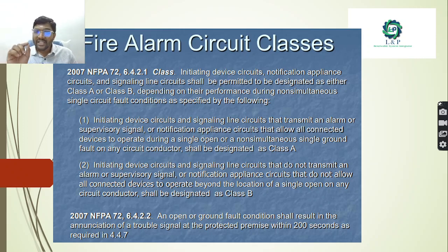Initiating devices and signaling circuits that transmit an alarm, a supervisory signal, or a notification appearance, and that allow all the connected devices to operate during a single open or a non-simultaneous single ground fault on any circuit conductor, will be considered as class A circuits.